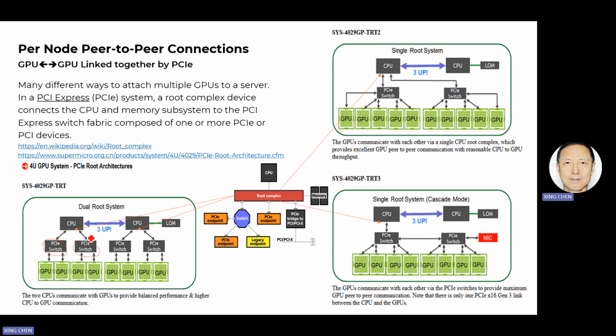It's a dual socket system, and then you have PCIe switches, and each PCIe switch is connected to 2 GPUs. So at the end, you can have 8 GPUs for this particular server. And this one, each PCIe switch could be connected to 5 GPUs. And finally, you are going to have 10 GPUs for this server.